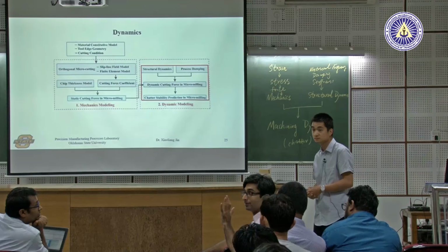If we check the FFT of this time domain data, we can see all the peaks. We can verify the major peak at the tooth passing frequency. It's much higher than the others. But you are measuring 0.1, 0.2 or whatever forces. Your drifts will be like that if you just leave it a little bit.